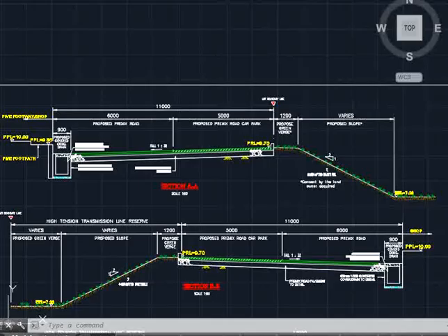We also mentioned that the construction work can only be done within the lot boundary. No construction work shall be allowed on the adjacent land unless you get the consent from the respective landowners. By all means, you should not disturb the existing conditions of the adjacent lot. You will need to prove that you have successfully acquired the consent of the adjacent landowner if the construction works involve the adjacent lot. Otherwise, during submissions to the Land and Survey Department, your submissions will not be able to get through.